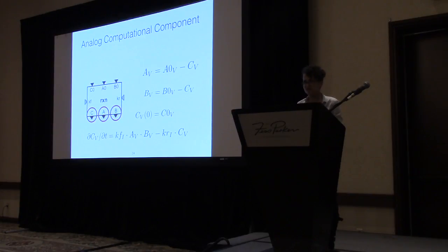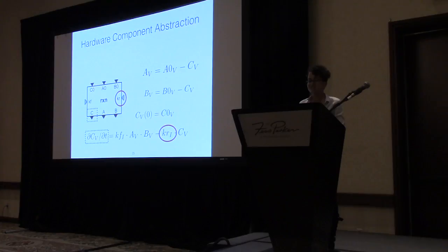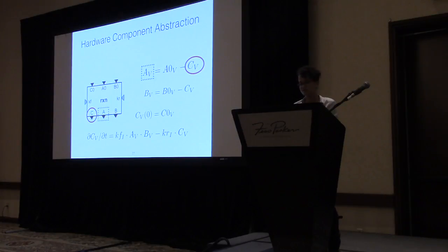And now you can see why analog computing is such a great platform for implementing dynamical systems. They directly implement the kinds of continuous dynamics that are necessary to model differential equations accurately. The relations that govern these dynamics of a port property could be a function of the current of an input port, or the voltage of an input port, or even a property of another output port. What this does is it creates a cyclic dependence between output properties. In this particular case, the cyclic dependence is caused by feedback within the analog circuit.